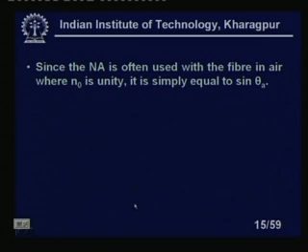Since the NA is often used with the fiber in air, n naught is actually unity, because the refractive index of the air is taken as unity. So, it is simply equal to sin theta A.